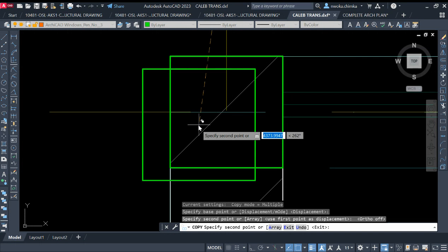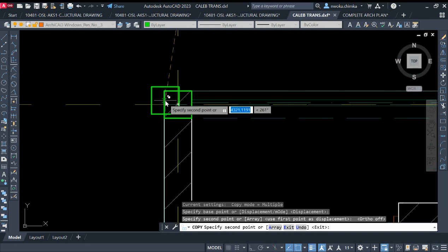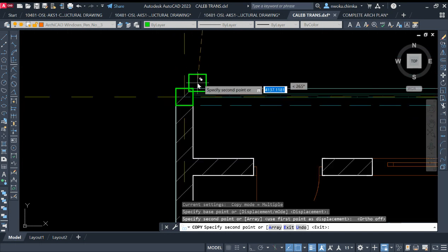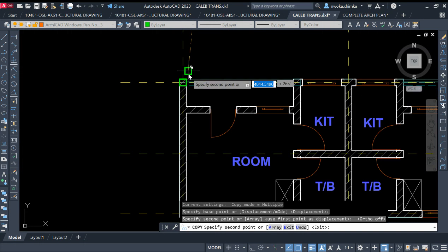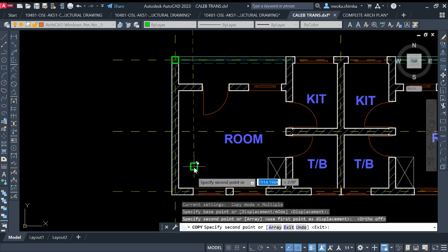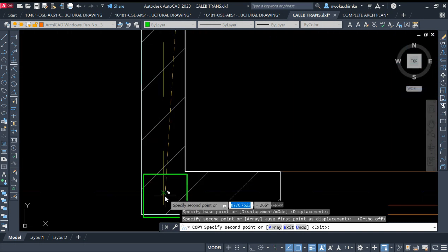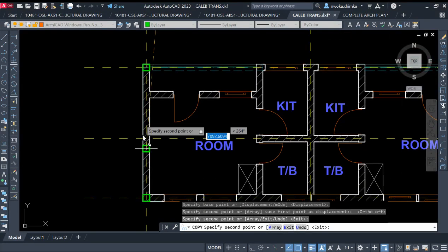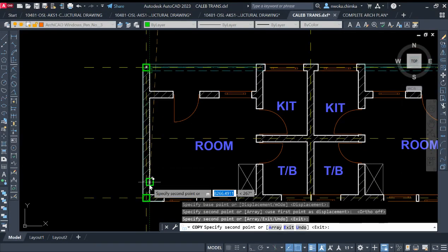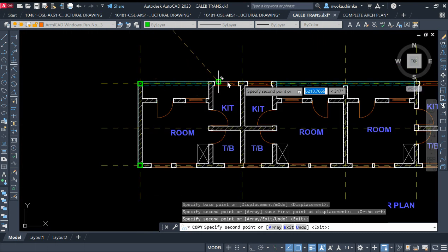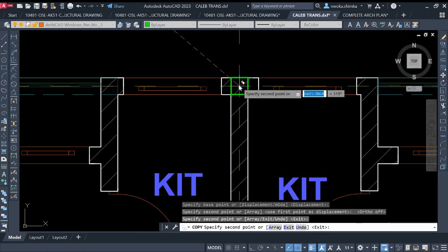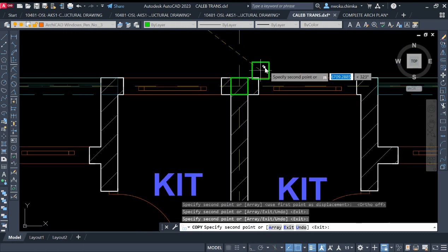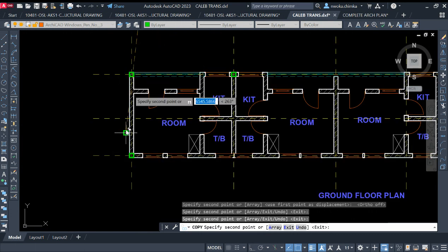Now, placing of columns as a structural engineer depends solely on you. You have to decide where you want to position your columns. Nobody can tell you what to do in this area, so that is why you need the knowledge of position of columns. The only thing I'll tell you is that when you're positioning your columns, as a fresh engineer or as a beginner in the design world, you should make sure that your column distance as a beginner structural or civil engineer should not be more than 6 meters.